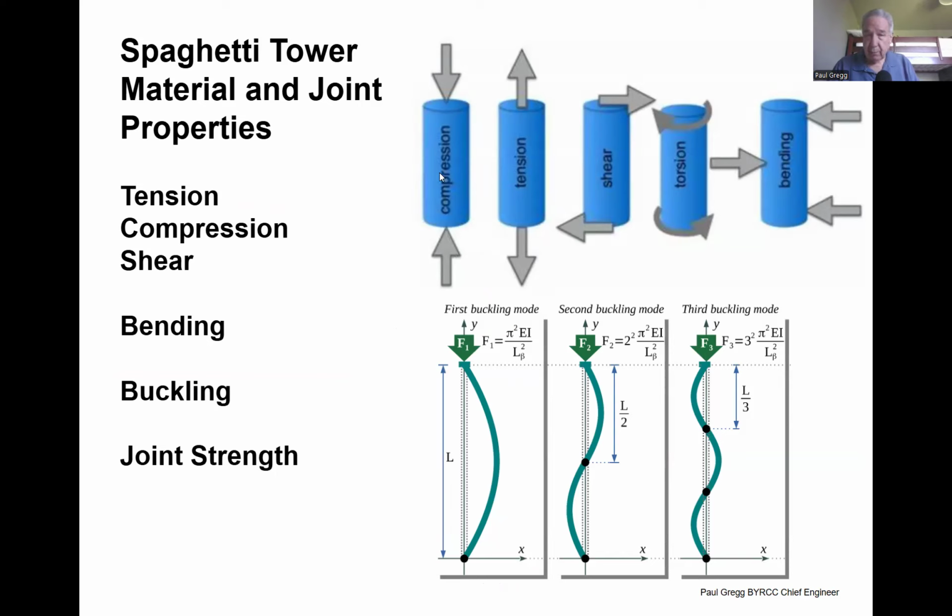All materials have a compression strength, a tension strength, and a shear strength, and that's kind of what these pictures look like. Torsion is kind of an extension of shear, and bending is an extension of compression, shear, and tension. A lot of times the bending test is not as useful, because it's not the pure compression, tension, shear properties. It's a combination of those things, and sometimes it can be difficult, but it's a great test for comparing different materials. And I'll go into it.